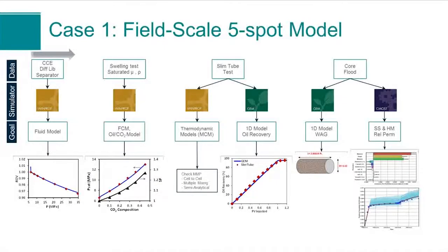So case number one is for your reference, and it's showing a step-by-step procedure to make a reservoir model. For this case, what I did was to match or create a PVT model based on the available data or lab data for the reservoir fluid. I had the data for CCE, differential liberation, and separator data, and I created a fluid model in which I could match all of the data.